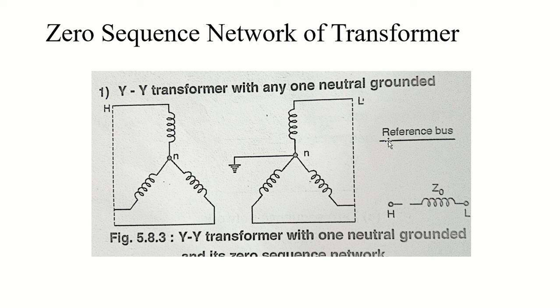So what will these observations be? The first observation is very obvious. Whenever we neglect the magnetizing current of my transformer, the primary would carry current only if there is current flowing in the secondary side. If there is no current in the secondary side, the primary will not be able to carry any current either, which is a very basic thing if you know about transformers.